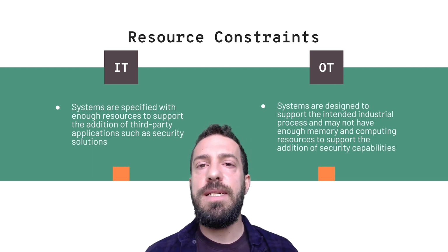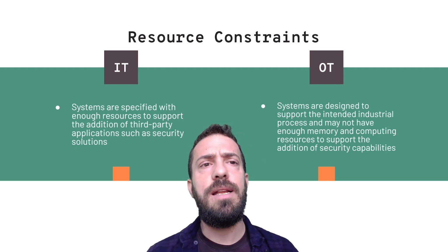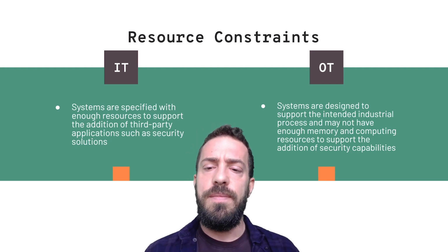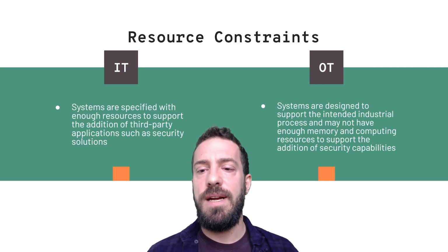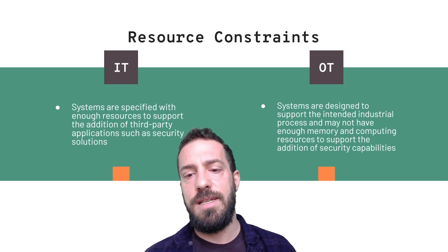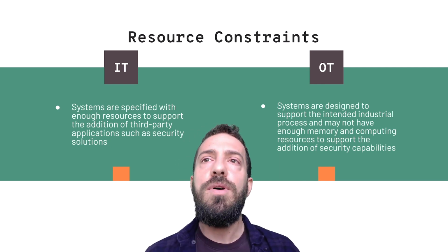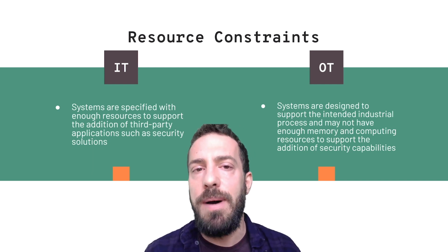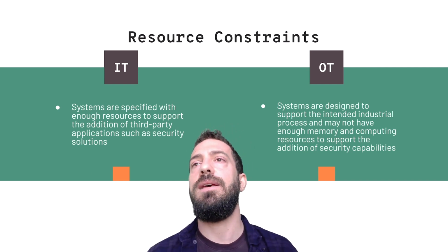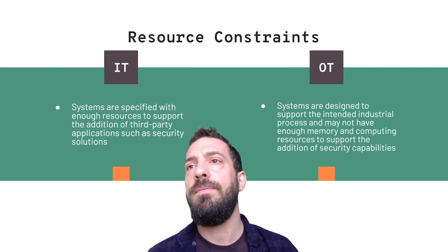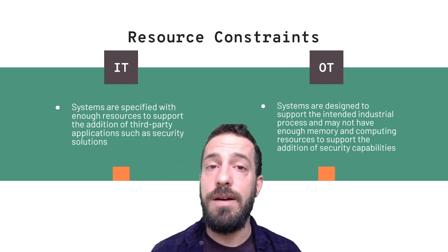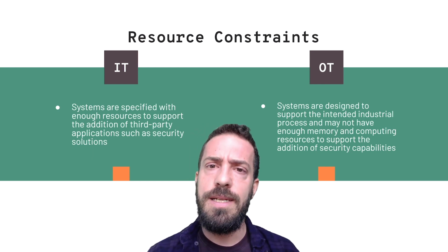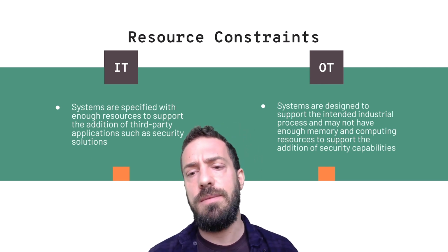The PLCs we've been seeing, and even though this is changing, right? But again, PLCs, controllers are staying for many years. They were designed to support something very specific, and that's an industrial process. So the memory ranges we see would not exceed 256 megabytes. And the processor frequency wouldn't exceed, say, 500 or 600 megahertz. So we've been doing some research on PLCs, and these are the typical CPU frequencies and memories we see.